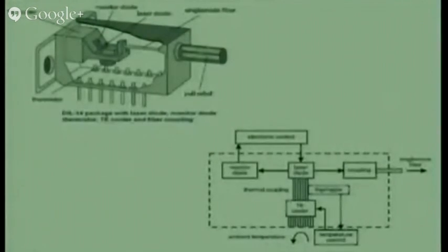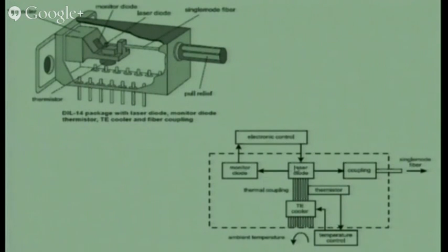The output or the Q point which is coming now, after 2 years it should be the same. So I look for monitoring by a photodiode, and then I give a feedback to the PN junction, so that my current which is giving the output will be maintained constant.